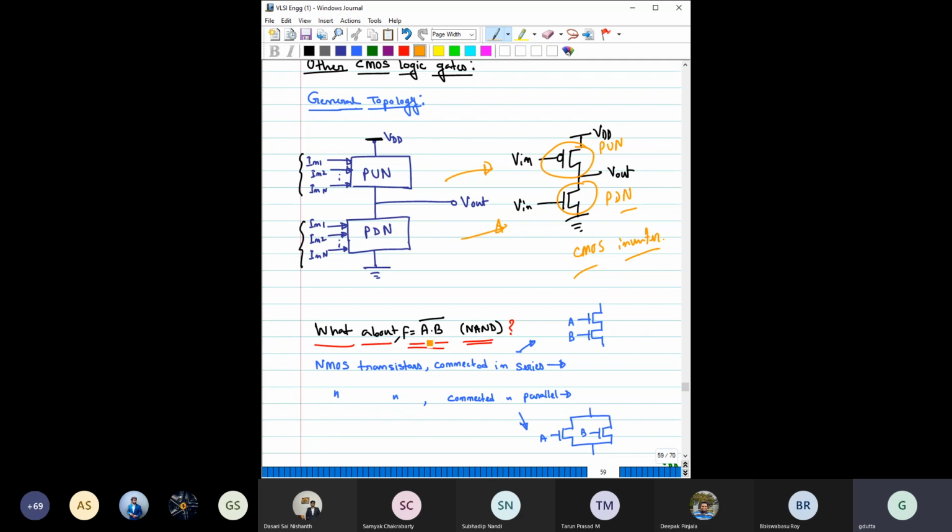So obviously, you can see from here, this is a two-input NAND gate. If the Boolean function it is implementing is f equal to a dot b bar, there are two inputs, and two inputs means you have to use more than one NMOS and more than one PMOS. So let us see how the MOSFETs, NMOS and PMOS, will behave when you connect them in series and in parallel. You cannot connect them any other way; you have to connect them either in parallel or in series. So let us see that.